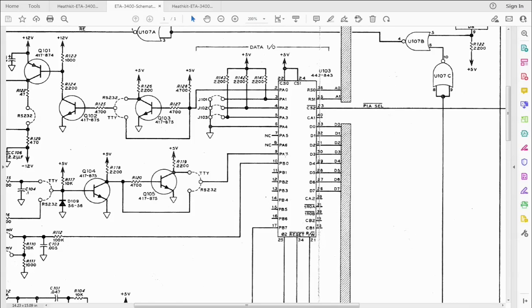The serial communication, the low-level stuff, is done in software using a method called bit banging. And as you can imagine, it gets a bit hairy because the processor can't really do anything else, because otherwise the timing will be off and it'll drop bits and bytes and all of that. But I guess it was deemed to be the best usage of hardware to use a PIA rather than an asynchronous serial controller.